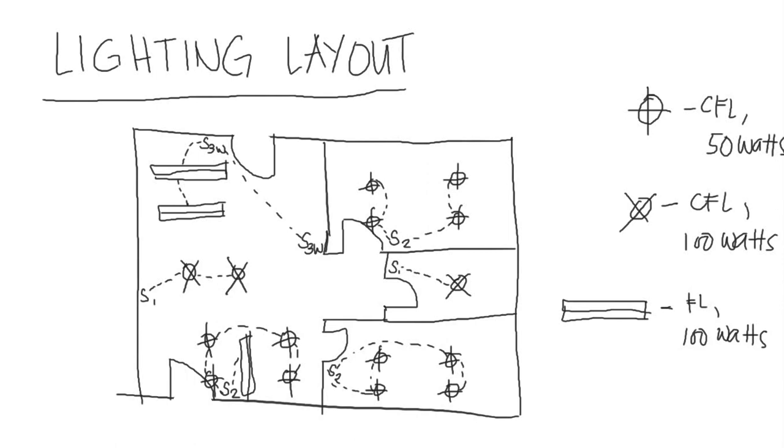To make the connection of the line from lamps to the breaker, you should use a continuous line, not the broken line. So the broken line is specified for lamps to switches, and for the lamps to breaker it will be a continuous line. So I will be using two breakers for this floor. So room 1, CR, and room 2 will be on one 15 ampere circuit breaker. So it will be like this, a continuous line.